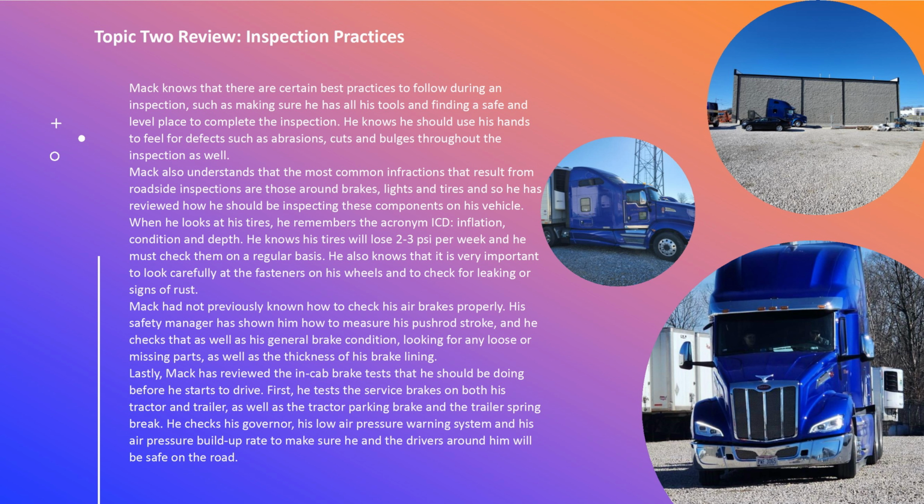Mac had not previously known how to check his air brakes properly. His safety manager has shown him how to measure his pushrod stroke, and he checks that as well as his general brake condition, looking for any loose or missing parts, as well as the thickness of his brake lining.